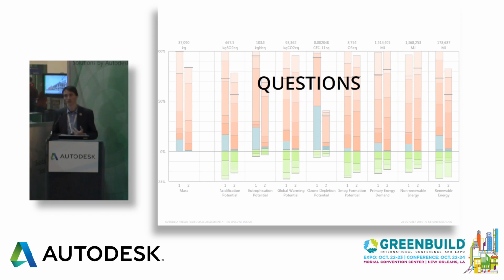I think there's also a recognition that our buildings are becoming more energy efficient, and with that comes a change in the proportions of the relative impacts associated with operations, namely energy use during the building's life, and the impacts associated with construction. And remember that the impacts associated with the construction are recognized on day one, the day a building is built, whereas the operational energy impacts are only realized over the life of the building. So there's that initial impact that you really do need to consider. That's the academic side of it.